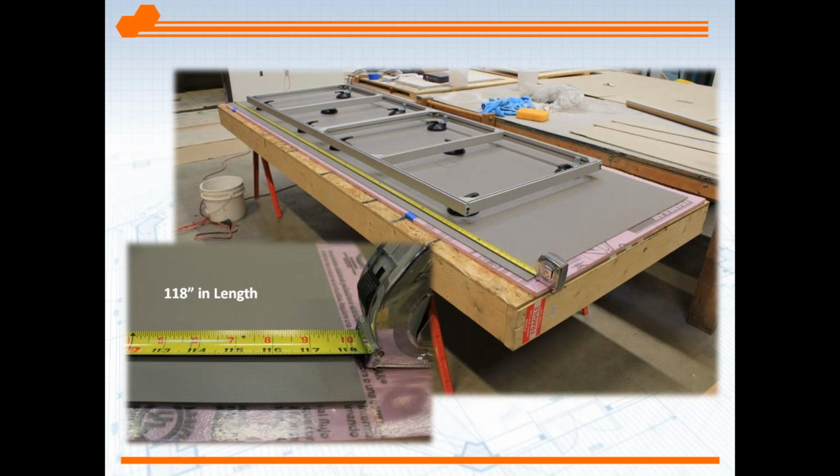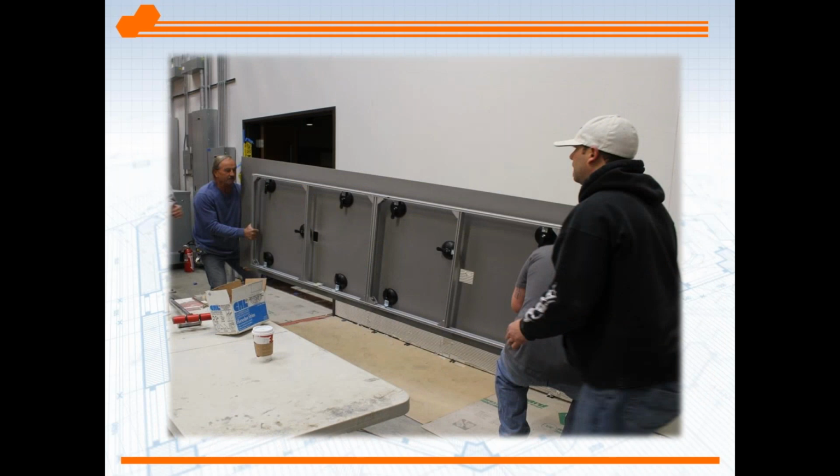Here we see a gauged porcelain on the table, and they're using what some call a glazier's rack, something you would use to move glass, to move this tile. It's a 118 inch long tile, that's about 9.5 feet, I believe, if I'm doing that right. And you see them moving it here. If they were to pick it up, it would be very difficult to handle. It may break under its own weight. So they use the glazier's rack, the same reason glass installers use it to move the product around.